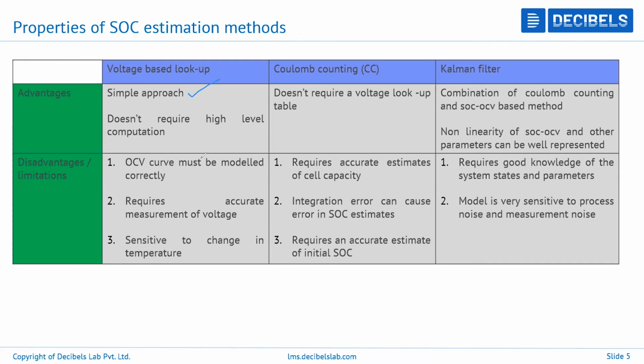The assumption here is that you must model the voltage to SOC values very correctly. The reason for that is that it is extremely sensitive to temperature and also requires an extremely accurate measurement of voltage. So again, this is very heavily dependent on the hardware, the capability of measuring the voltage to a very accurate value.